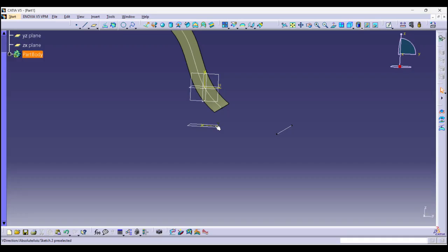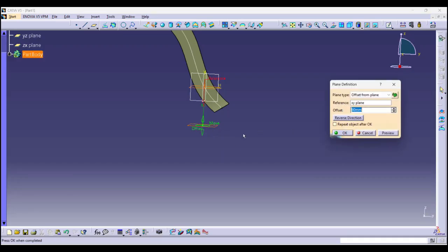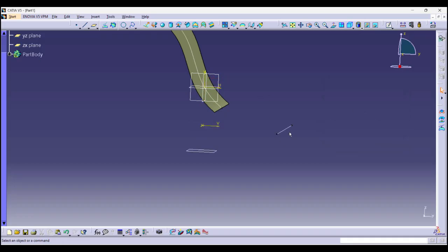So I think we need to take this plane little bit more lower side. So we'll edit the distance here. Instead of 60, we are going to take 100 mm. Say update and this line will get updated by the new position. We can see here the change. The line is coming at downside now. Earlier it was looking very much upside. So the surface might not have looked tangent here. That's why we have taken it at lower side little bit.